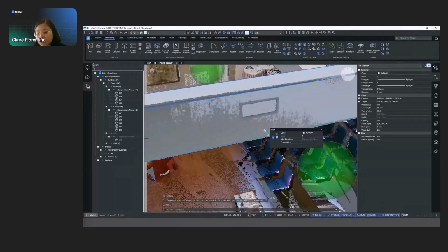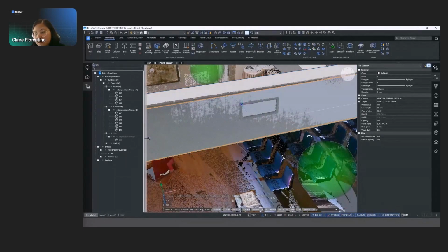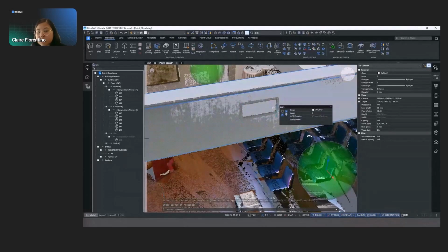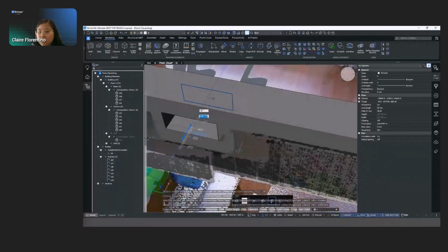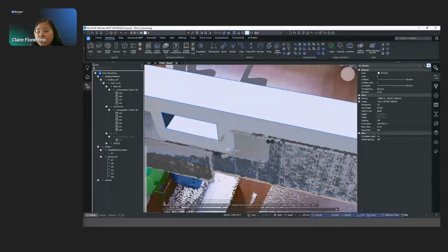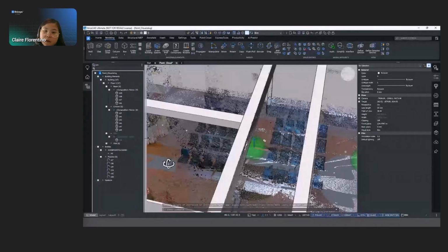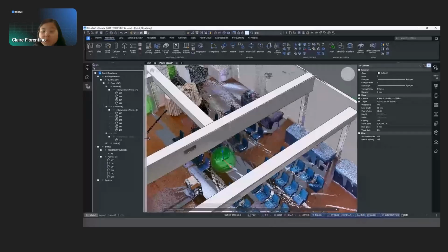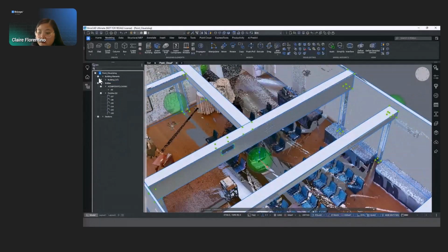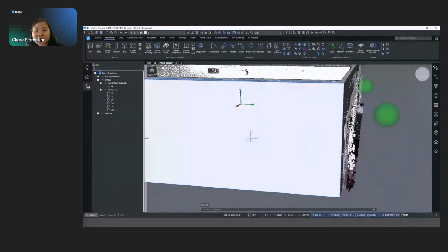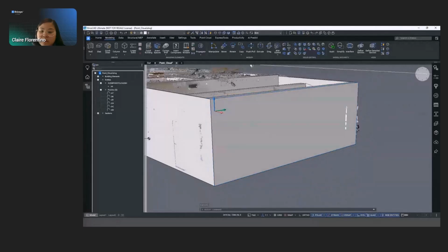So moving on now, we want to just every now and then go into the bubble views. In this case, we saw that there's this hole within one of the beams. This is probably a sleeve for certain either pipes or certain services that they have there. So you can also mark that in and extrude to subtract that portion of the beam, and then you have your sleeve. Again, if you notice, a lot of it is really just push, pulling, extrusion, and so on, right? Things that are very familiar.